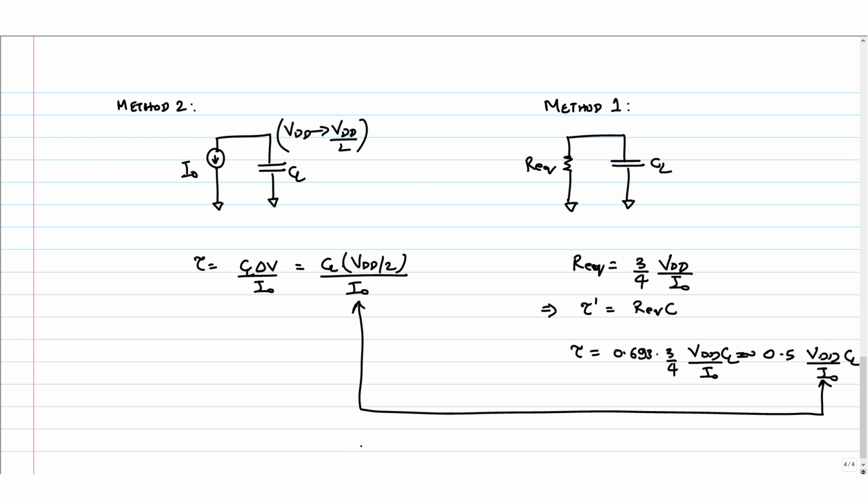right. Now obviously if lambda is 0, then the constant current source model is the right model, because the transistor is a current source. Okay, so if you look at the model that we are using for delay, this guy, V naught of t, will start from VDD and then go linearly, right.